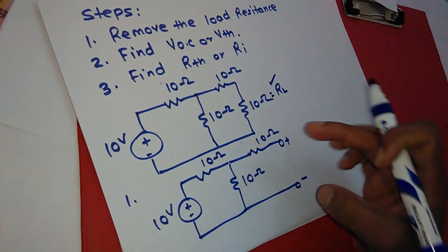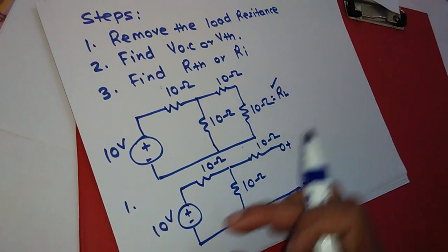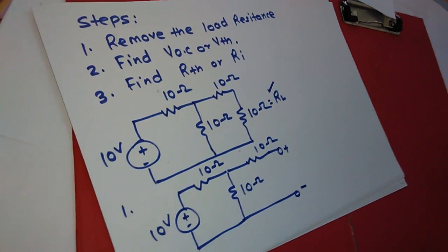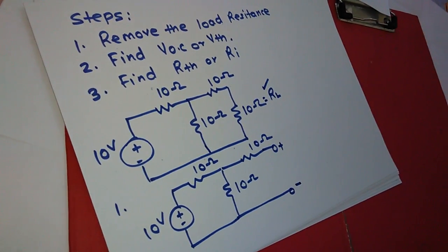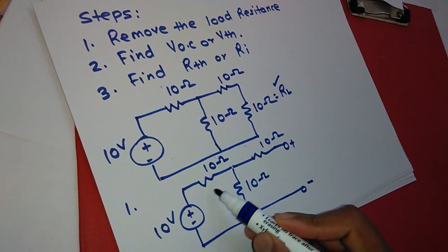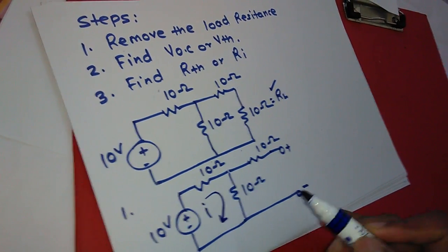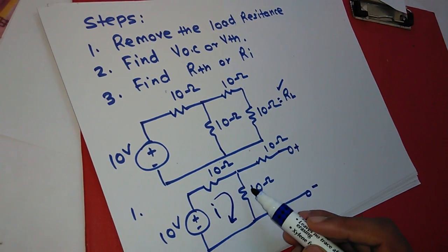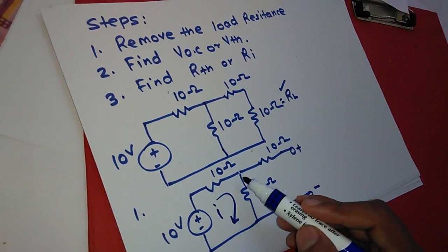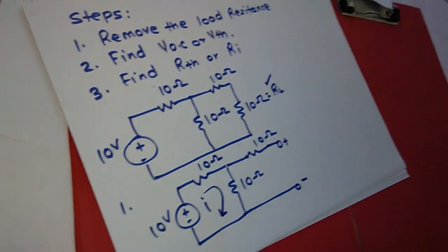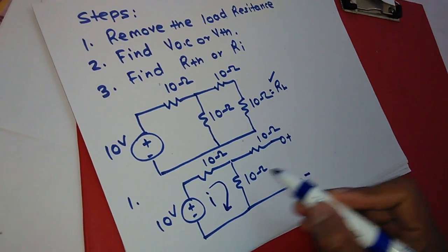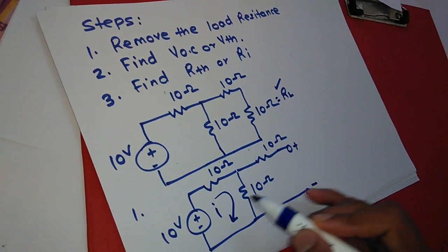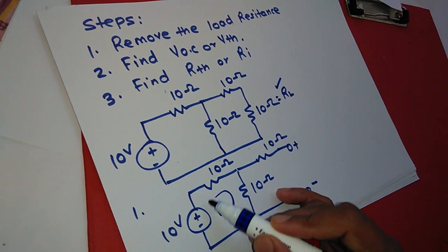Now we will find the voltage across the open circuit terminals. First, we can easily find the current flowing in the closed circuit, I. The resistances of 10 ohm and 10 ohm are in series, because current is not going through the open circuit terminals. Because there is an open path, no current flows in this path, so all current circulates through this closed path.